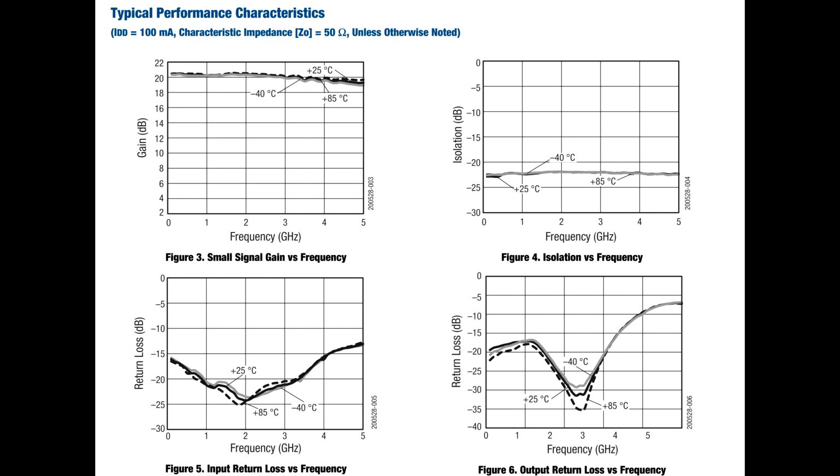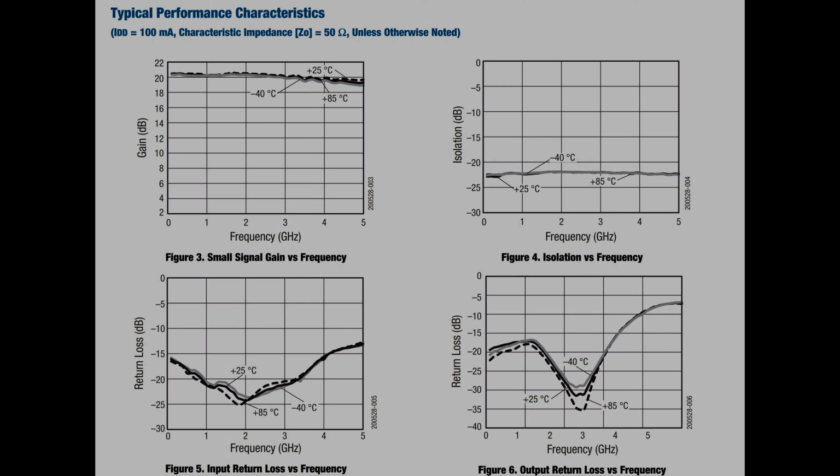The S22 performance degrades in the 5 GHz bands while the input return loss is still below -10 dB, which is quite good. The output return loss could be compensated by other means, but even then it is still a usable amplifier in the 5 GHz frequency region.